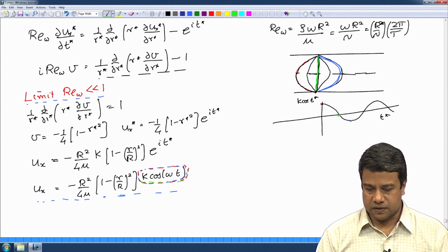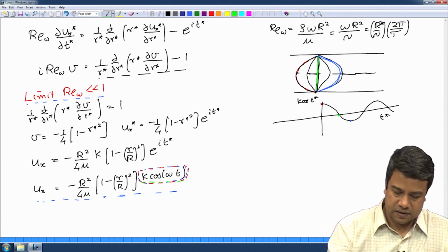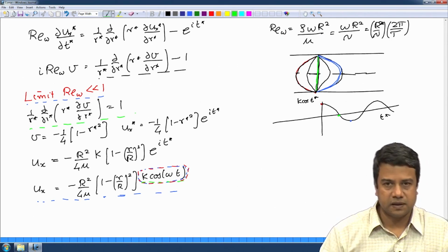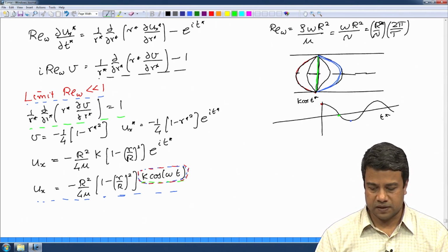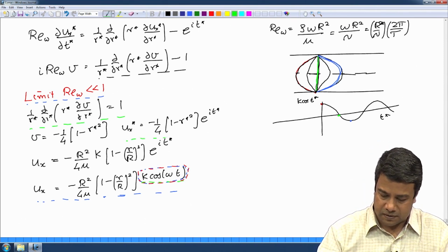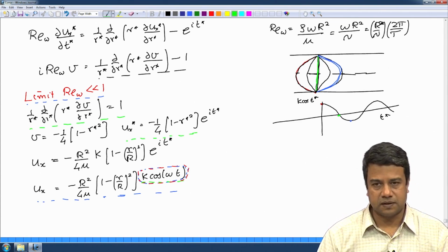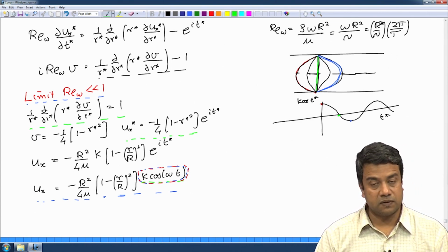First, when viscous forces are dominant, you can just solve this equation. If you recall, this equation has exactly the same form as the steady fully developed equation. The solution is therefore also a parabolic solution in the limit of low Reynolds number. I told you the physical reason for this.